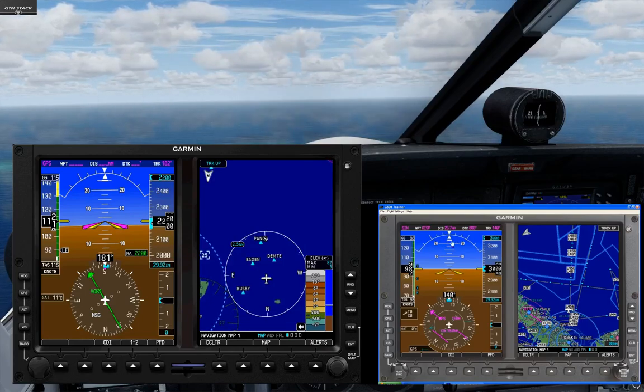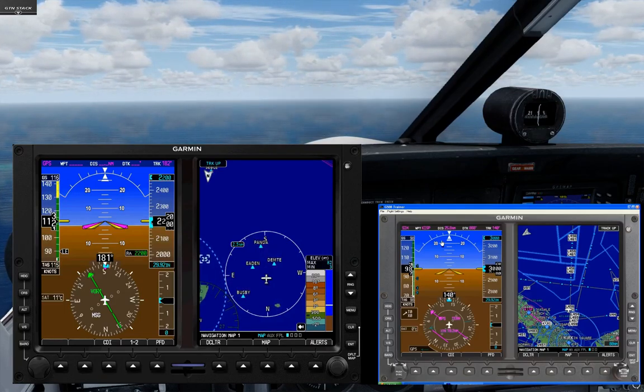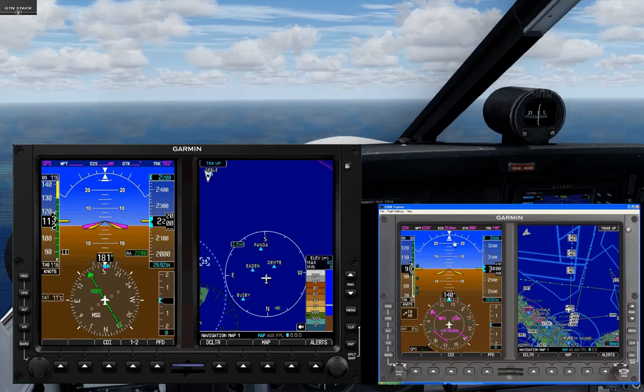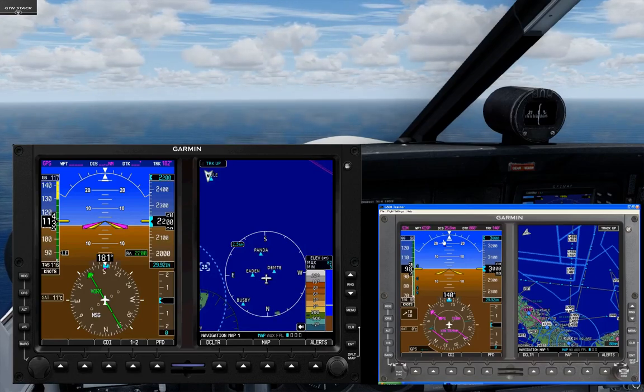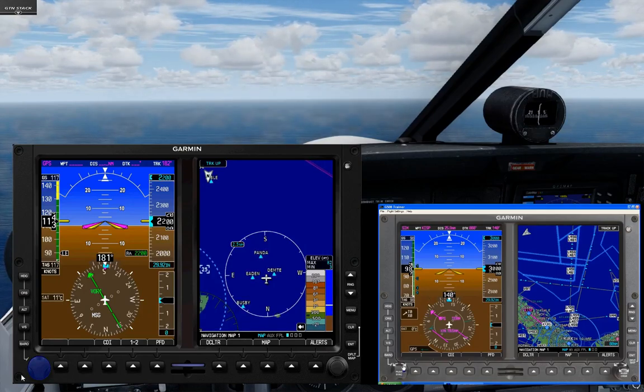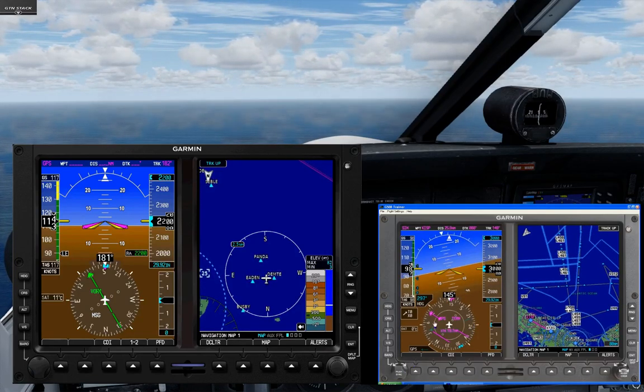If this brick slides left or right, it's presenting the same information you would see on an inclinometer, showing you that you are uncoordinated for that particular phase of flight. So keep the brick in the house, keep the brick centered, step on the brick, however you need to refer to it. It's giving you quality of turn information as an inclinometer does, and it acts the same way. So once again, we'll make a right-hand turn. We'll come all the way back to 300.